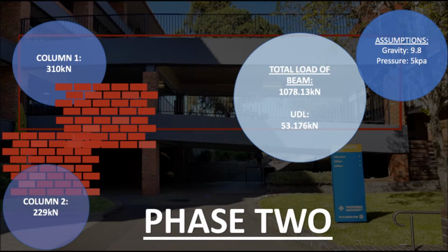In calculating the total force on the bridge, we use the formula force equals mass times gravity. The formula was easy to use as we had the mass of the bridge already and the gravity. Our total force load was 1,077.4 newtons and our distributed load was 57.3 newtons.